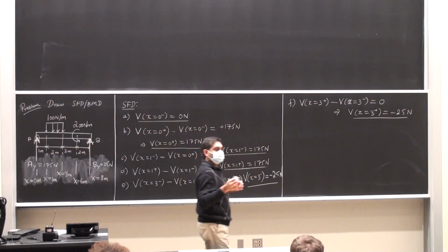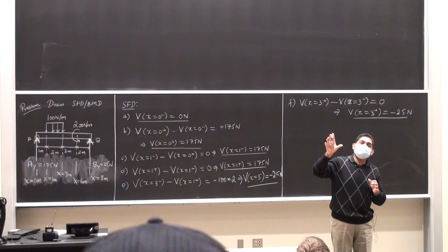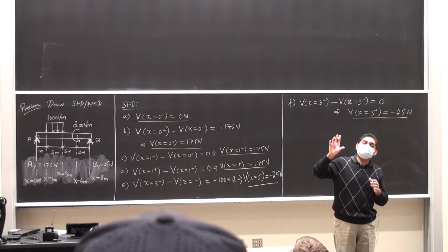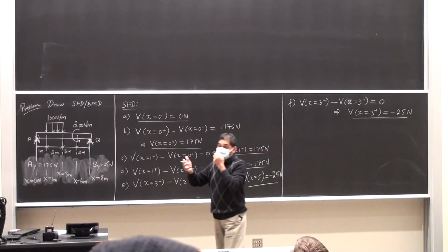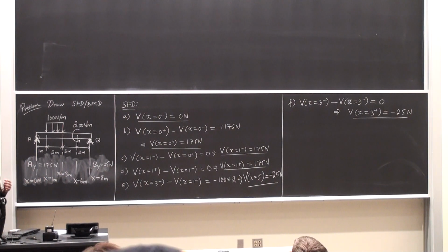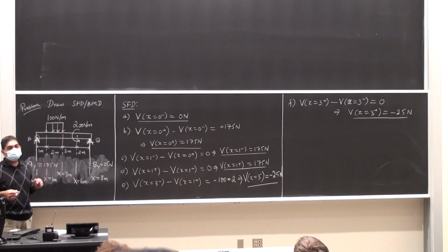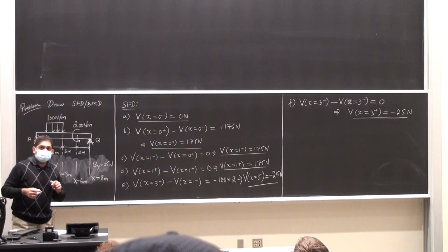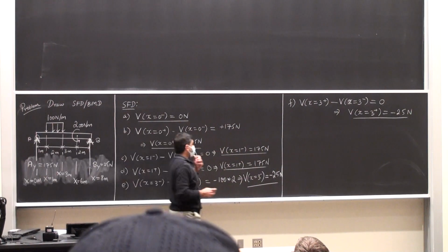Does this make sense to you? If you see a couple moment, it's not going to play a role in the shear force diagram. It has played its part in the calculation of the support reactions. It's not like it's not going to do anything to you. It has done its part. When you calculate support reactions, you would have had to include its effect. Okay? So, next step.